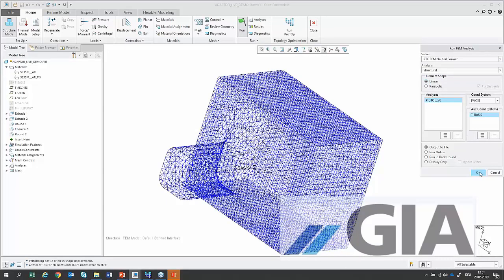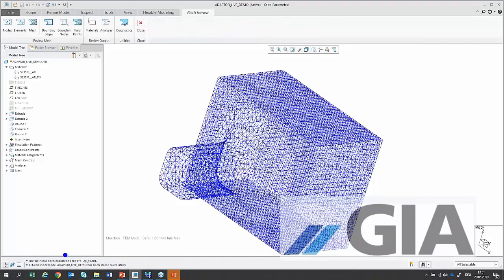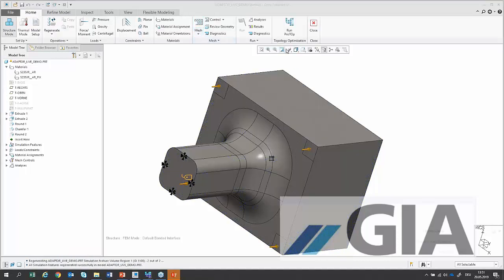Now I will save this mesh here as an input file for ProTOp. Okay, linear elements, and I'm writing down this FNF file, down there. Okay. In the version in July here, you can press this button in Creo Parametric, and then everything will be done automatically. But the other CAD systems work the same way to share the FEM, so the FEM input deck, with ProTOp.